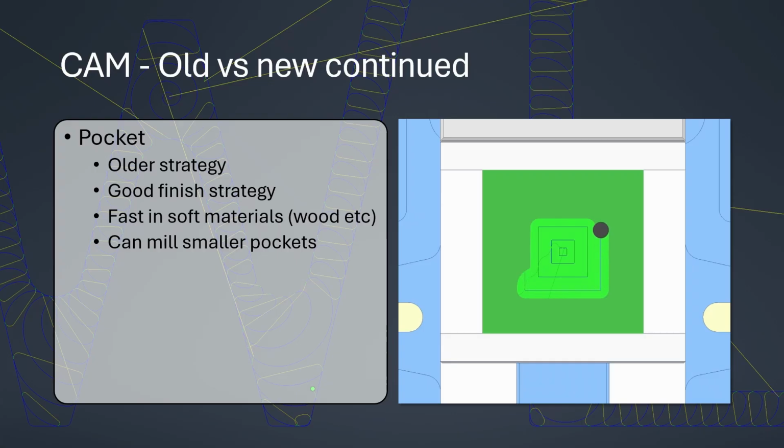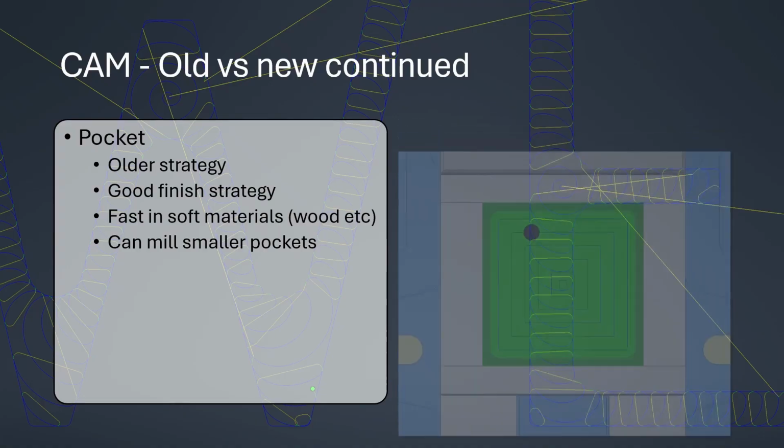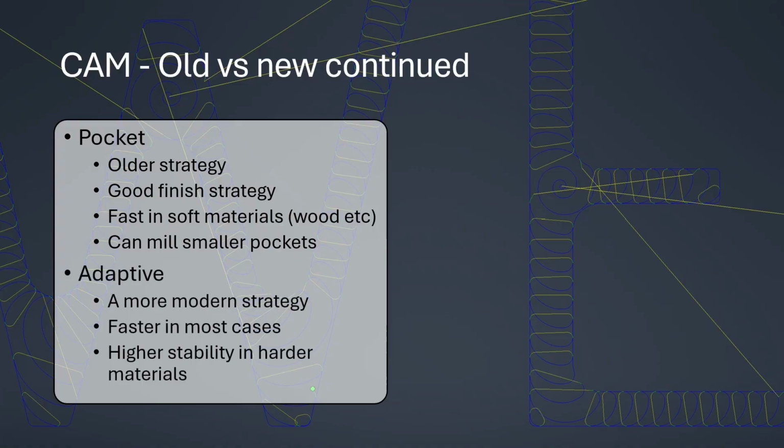So this is a pocket, a 2D pocket, as it were. And so you can see it's going rectangularly like this and milling out full diameter in this case, or slightly less actually, but almost full diameter. And so you can see in this case you needed to do 2 steps. Adaptive is what the operation is called for when you're doing the more modern high-speed machining type.